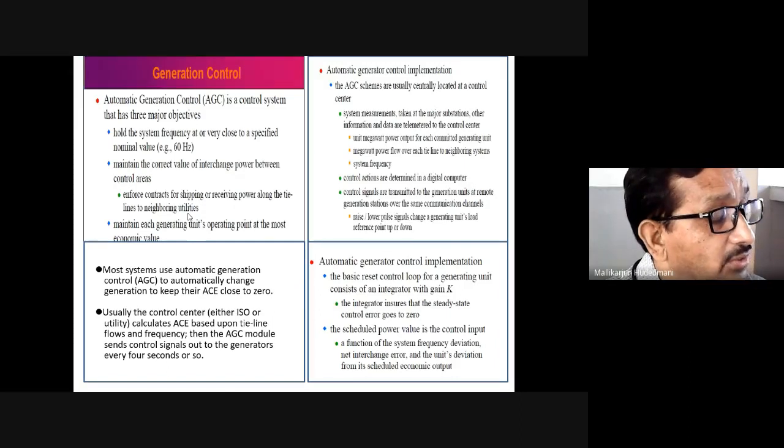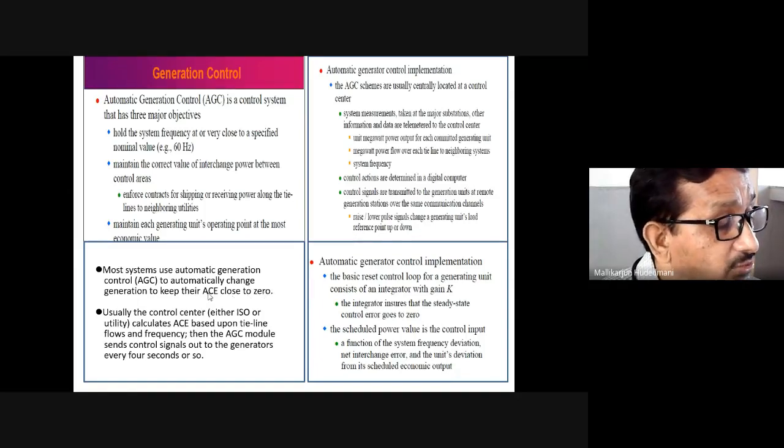Its demand we know, what it has to meet. Any mismatch between these two is called an error. That error has to be nullified, brought very close to zero, which means what you are generating is actually meeting the requirement. Your system is under steady state. That's what is called area control. We'll see its magnified view in the upcoming slide.